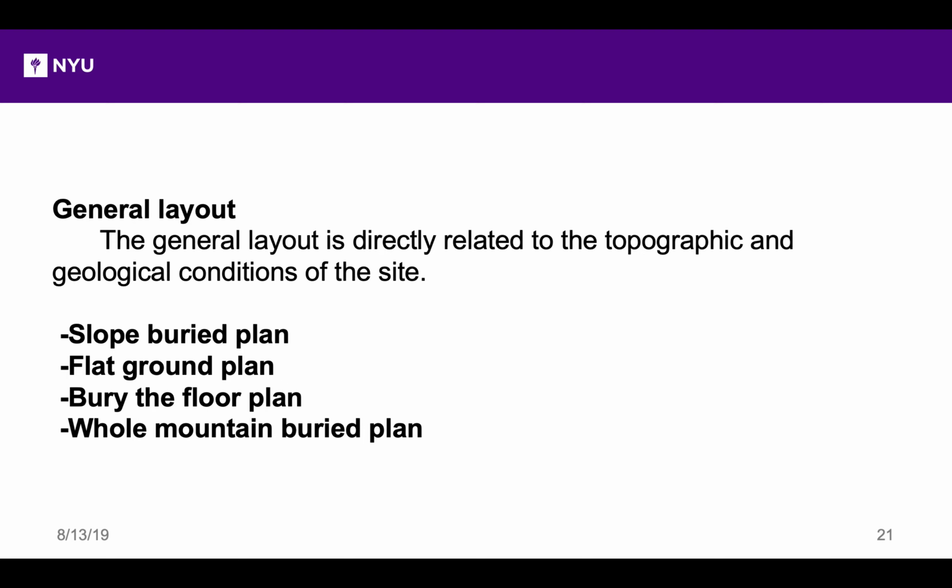Due to the huge structure size of the cooling tower in the secondary cooling mode, it is not suitable to arrange it in the mountain. The once-through cooling mode should be adopted, to divert water from nearby water sources for cooling.